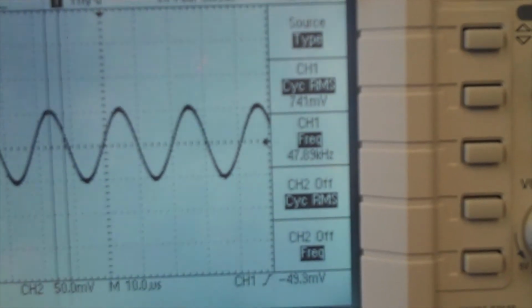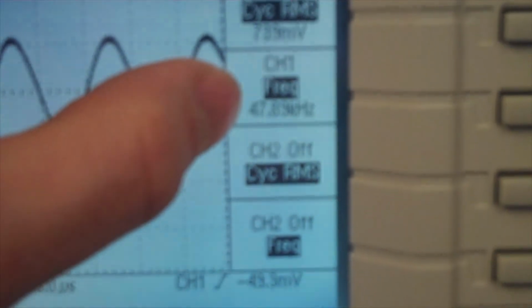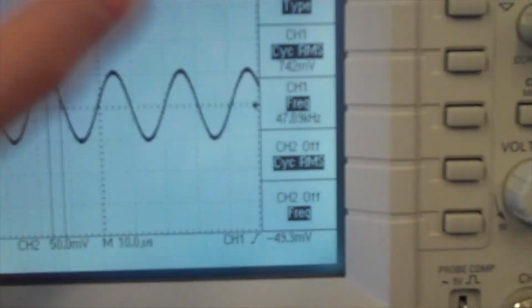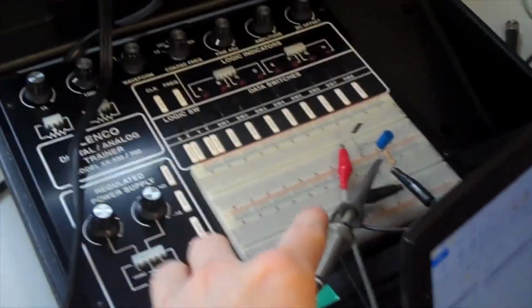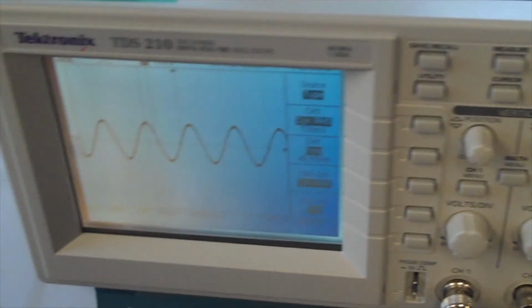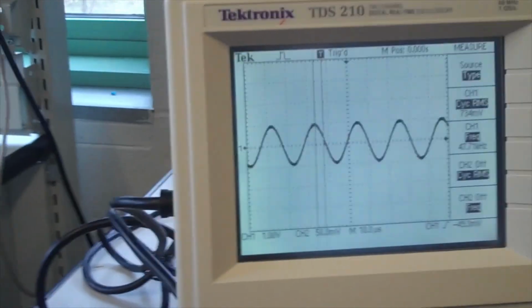So somewhere around there. You're going to record this frequency. The lower frequency will be omega 1, and the higher frequency will be omega 2. Now all you do is switch this into a parallel circuit and follow the same directions, and use the different equations.